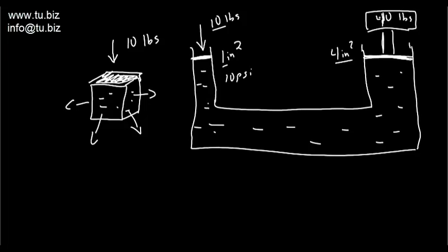You're going to be able to lift 40 pounds of force on this other side of the container by applying only 10 pounds of force on this side. That's how you multiply the hydraulic power. You can say you multiply, you can say you transfer power.